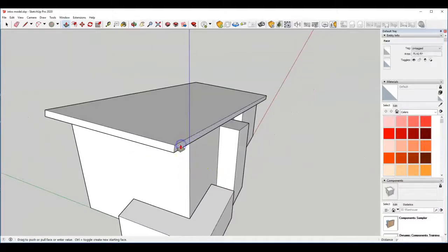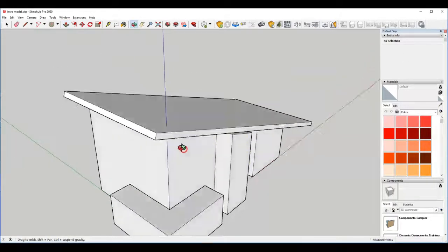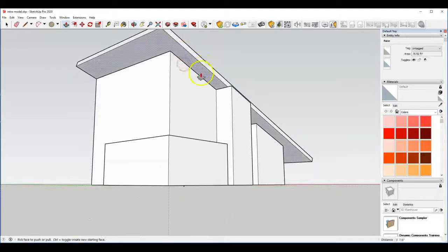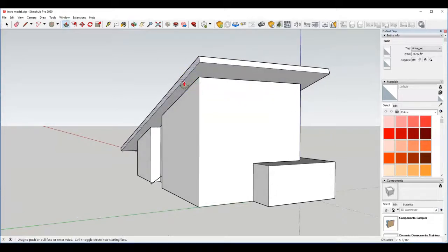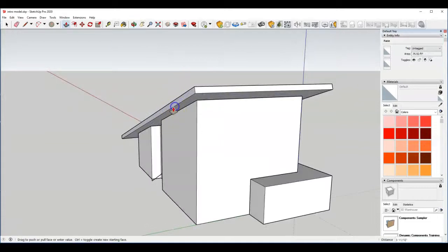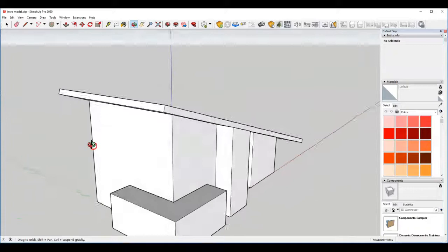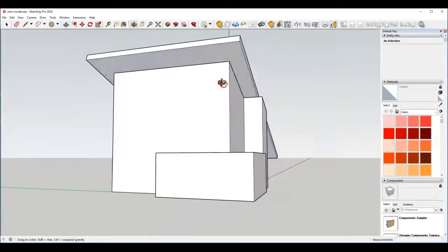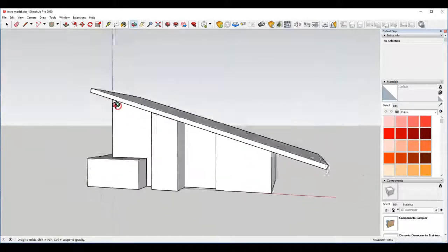And then ultimately I'm going to come to the side and push pull it through the front here. Now in my original design, this piece purposely stuck out further than the roof edge, and I'll have to fix that up in a later step, but just have it stick out a little bit there. And again, since I'm just designing, I really am just eyeballing. Now again, are there times in SketchUp where you want to be precise and use real distances? Certainly, but not necessarily during the sketching design phase. So I'm just going to eyeball that those two lengths are the same and say, look at that, looks pretty good to me for that main shed roof.